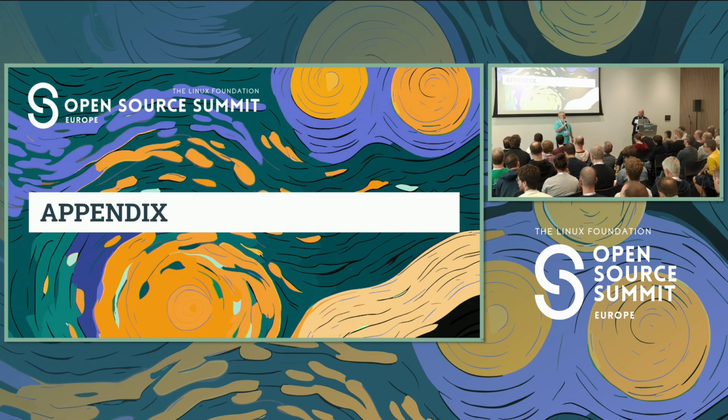Yeah, I mean, the BeaglePlay, when you boot it, it gives you four or five options on how you want to boot, like a debug mode or from your SD card, eMMC, et cetera. So I don't think there's any reason why you couldn't match against that, like you do with U-Boot, and pick the option depending on how you actually want to set things up.